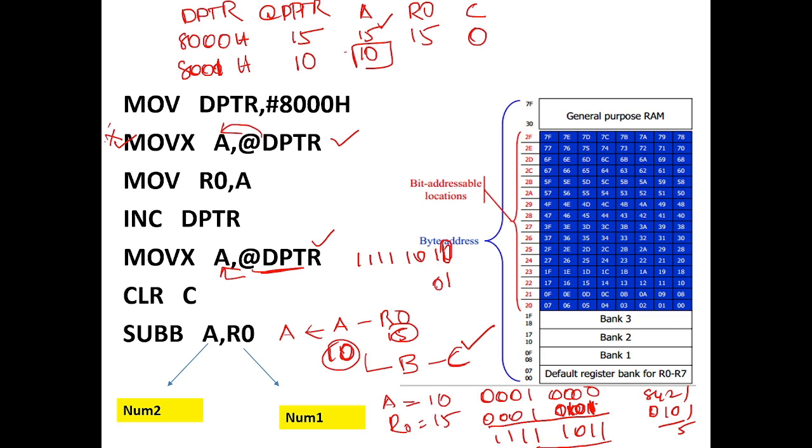That is 10100000. So this is the 2's complement of this number. That means you get 05. So you can see your MSB is 1, your answer is 1. That means magnitude is changing, so minus 5. So you can get this number minus 5.